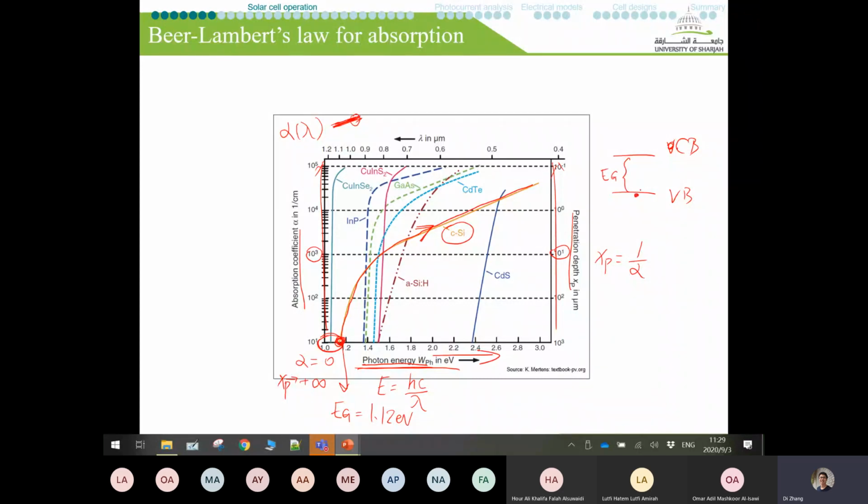If you want to excite the electron from the valence band to the conduction band, and the photon energy precisely equals the band gap, then yes, it's possible to have absorption. But at the same time, you need exactly this amount of photon energy to make the excitation possible, so you have very little margin for error. Any additional losses or any deviation will make the absorption impossible.